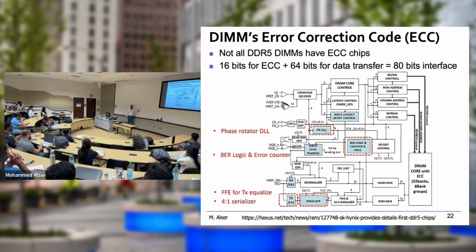There's what we call a Rowhammer defense mechanism. So in recent DRAM chips, we already have this mechanism implemented in the ECC itself. That is one of the hacks or attacks that we can solve. However, until now, there is a lot of research showing that it's not solved yet. They could solve it in certain scenarios. For example, if you are targeting to activate the same row repeatedly, then the ECC is going to block your request for some time. It's going to impose some relaxation between the requests.